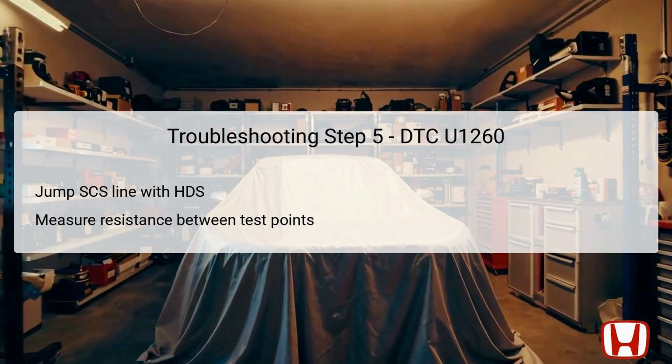Resistance should then be measured between specified test points in the auxiliary pump connector and the TCM connector. Establishing a reading of 1.0 ohm or less confirms that the EOP-SIG wire is intact. If not, an open circuit needs to be repaired to ensure proper communication.